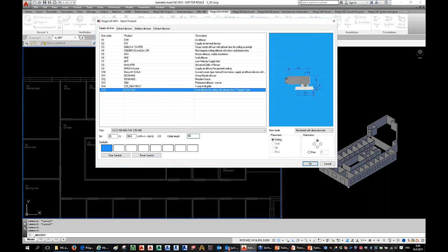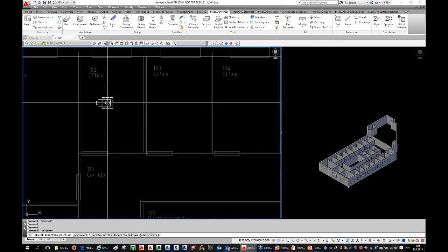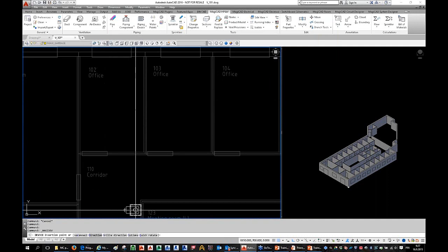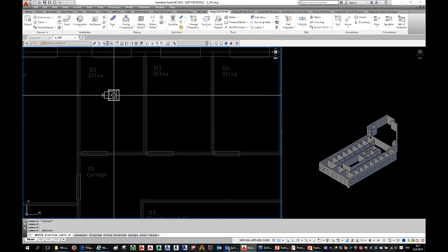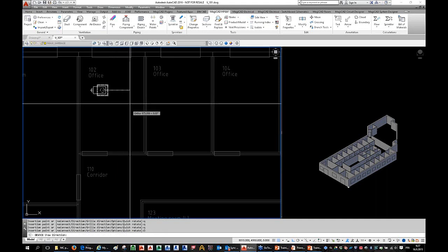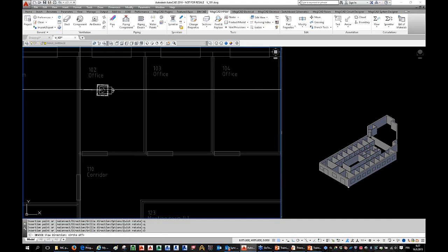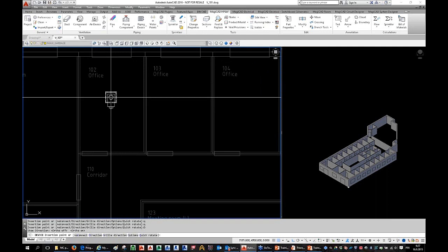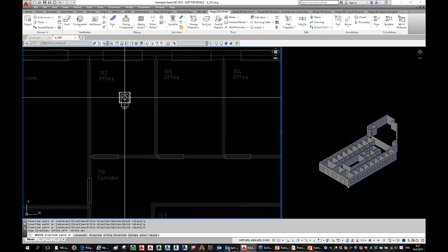And you can change all of these settings afterwards also. Then I just click OK, and the device is coming to my drawing. First I have to rotate it. I can rotate it with clicking Q and space bar on my keyboard, or right clicking and selecting direction. If the ortho is not on, I can basically rotate it any way I want. Okay, when I've rotated the device to the correct direction, then I will install it by clicking the drawing.